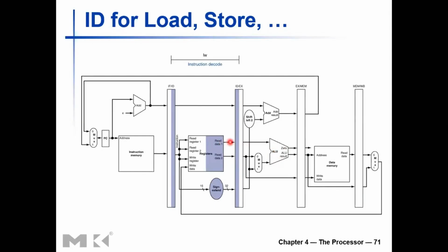So at the beginning of the clock cycle, you have some data here corresponding to the previous instruction. After a certain amount of time, which comprises register writing to the pipeline register, reading from the pipeline register, and reading from the register file, after that delay, you will have the new data values from the two new registers available here, right? So I hope that is very clear to you.